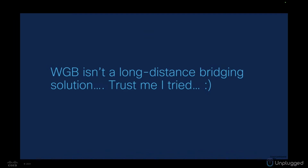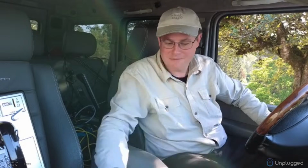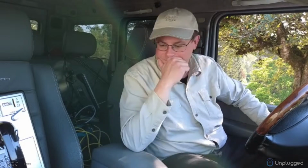I'll just sum it up to say that you want to keep your Workgroup Bridge links typically under a kilometer or two. Believe me, I tried. There's lots of slides to back that up, but anything over that, you're going to start running into ACK timing problems. Yeah, the protocol is not made for that.